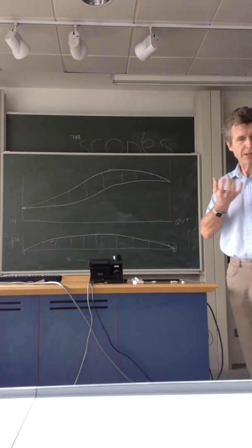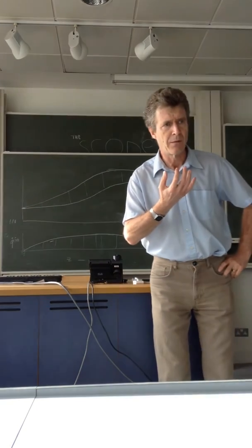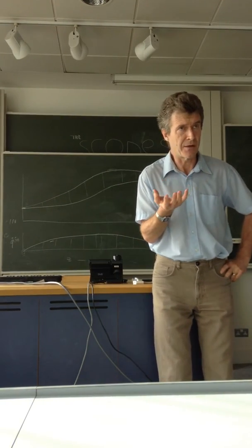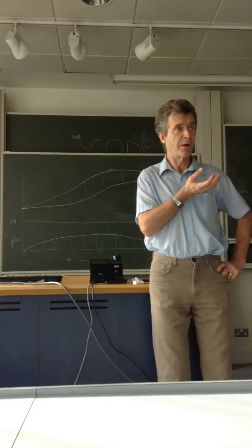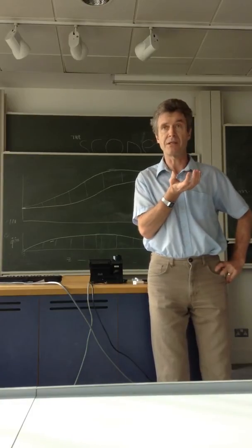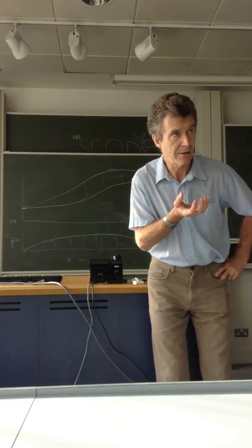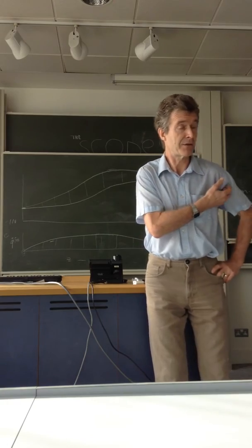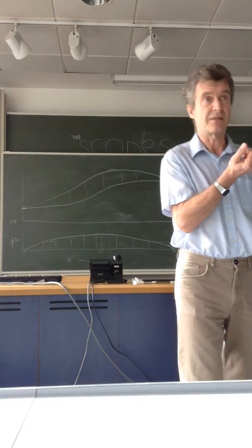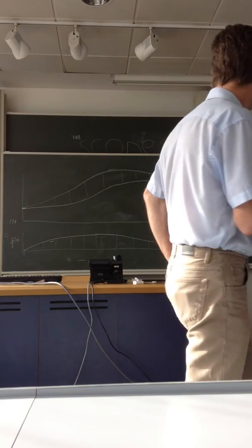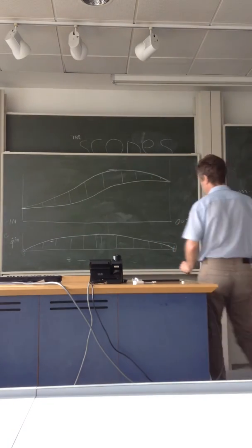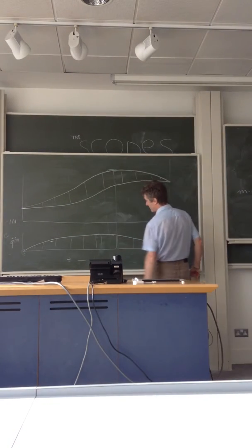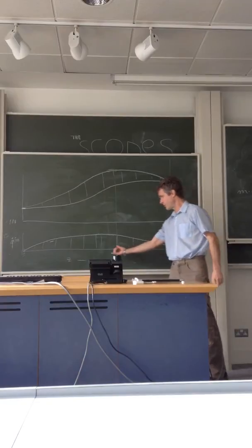And then the last thing we did on that particular thing was to say, well, what we mostly want to know, obviously from an engineering and safety design point of view, is where is it hottest and how hot is it? So having got that expression for the axial variation, we can differentiate it to see where is it maximum, which finds us this Z location here, which is typically about 60% of the way up.